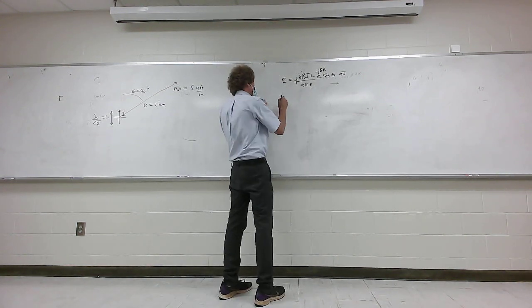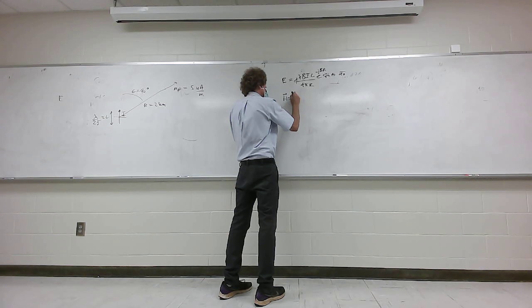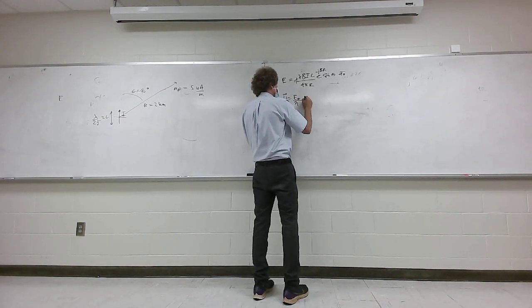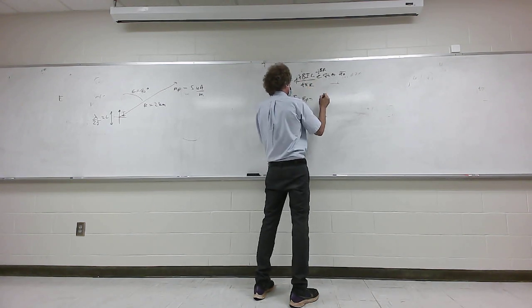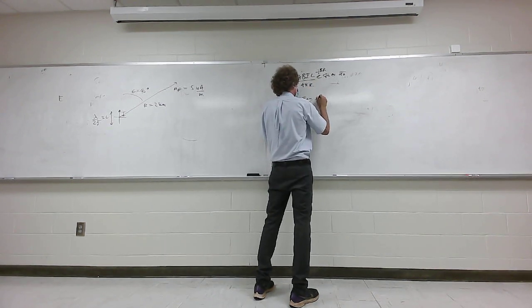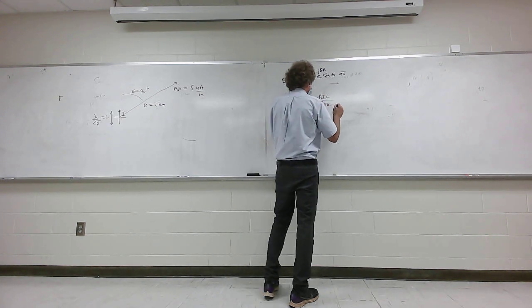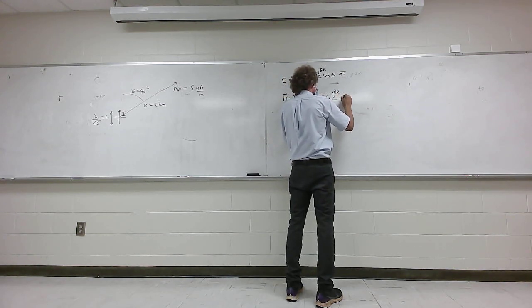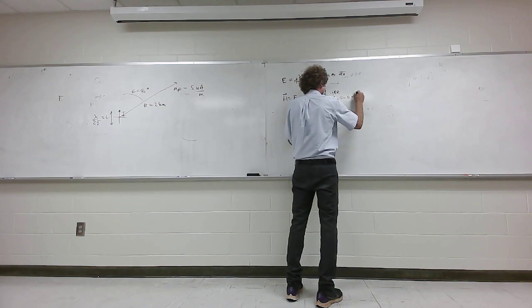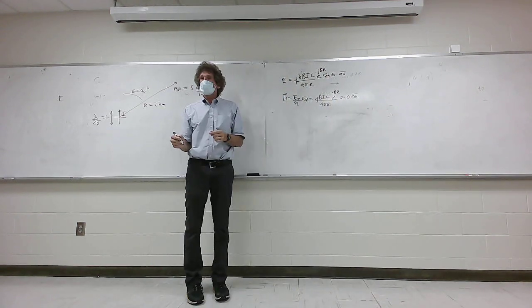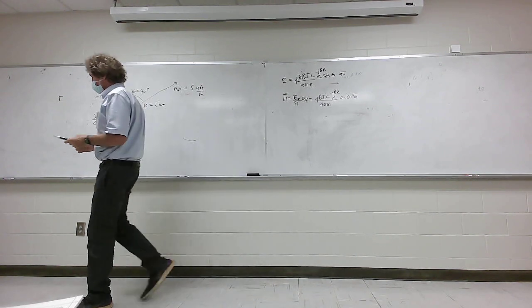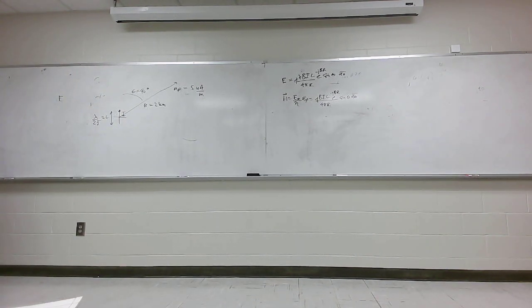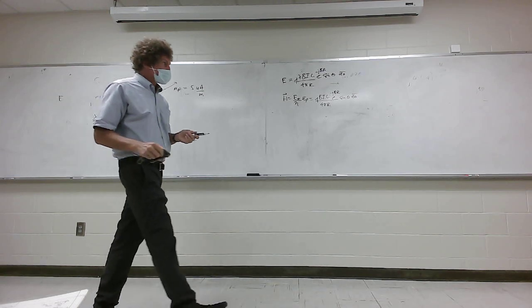That's understood. I know H is just that E field in the theta direction divided by eta, and it's in the a phi direction. That means I get rid of that, so that's j beta IL over 4 pi r e to the minus j beta r sine of theta a theta. Now I've got the general equation for the H field at any range in the far field. Here's where the fun begins, and it's not hard to see.